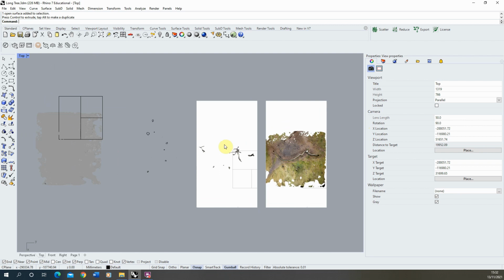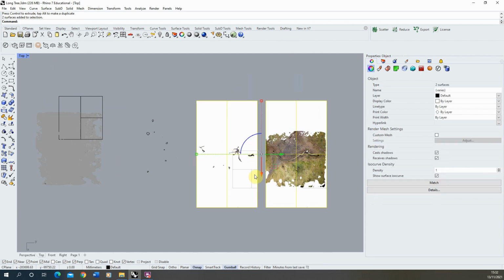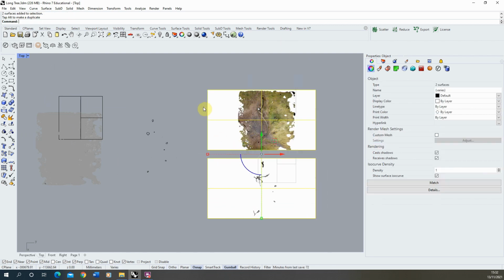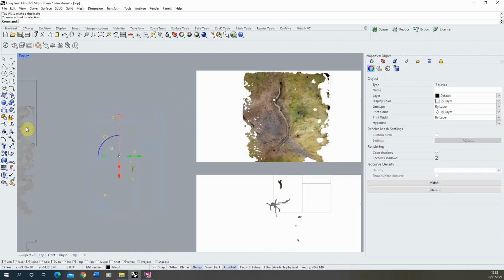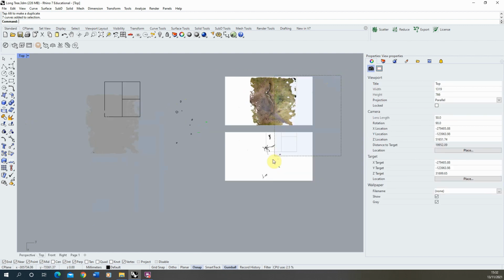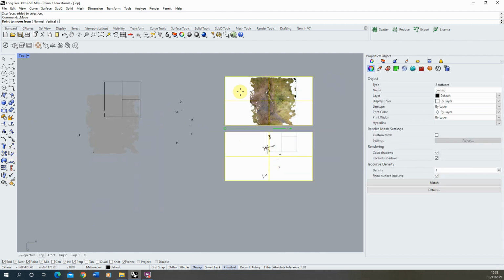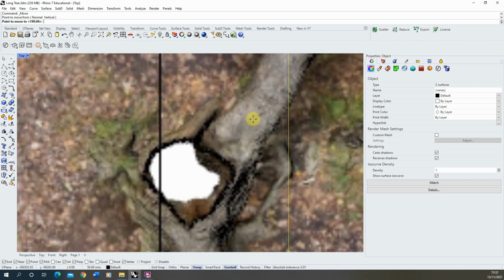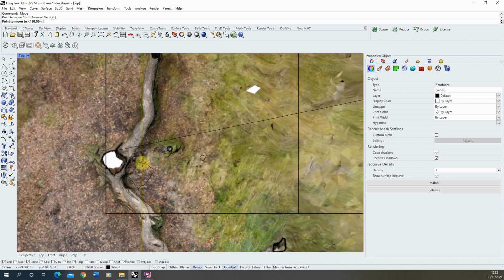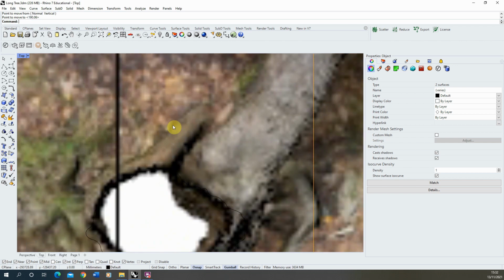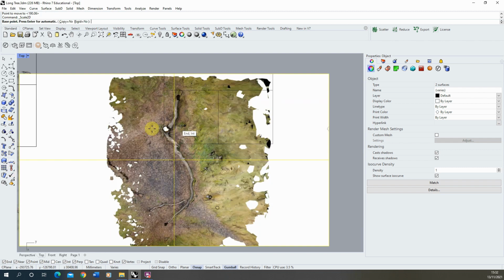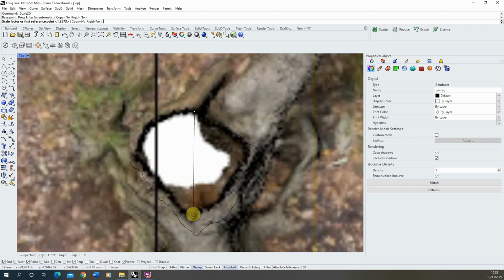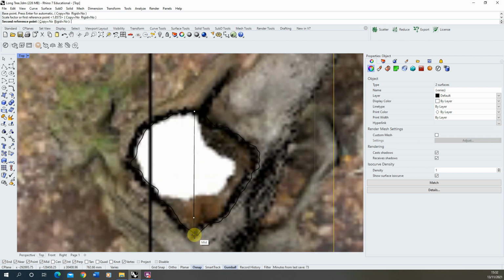Now what's happened is they've come in actually at a 90-degree angle to my view, so I'm just going to rotate these around so they match. And now I need to line up my cut line with this drawing. So what we'll do is I think we'll move the view underneath the cut line there, and I'm going to try and sort of just snap it to the big piece here. So we'll kind of line up the ones we can see, and then making sure I've got both selected, we're then going to go scale 2D again,